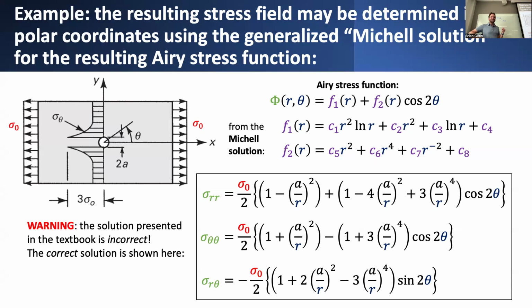But one clever guy, Mitchell, came up with the fact that for any plane stress problem expressed in polar coordinate form, there is a truly general solution which satisfies compatibility automatically. So you don't have to check the compatibility condition. The only thing that you have to enforce are boundary conditions. So you do still need to enforce boundary conditions, but otherwise it limits the potential solutions for the Airy stress function to a small subset of possible functions that will automatically satisfy all the other conditions.